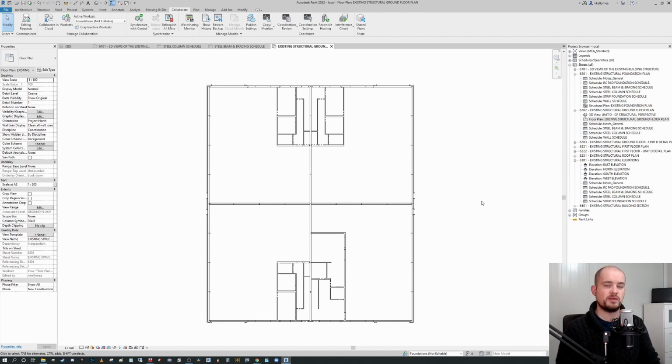And historically Revit, when you got to larger scales, lost a lot of finer detail. So if you had a very large facility, let's say, or a shopping center or something like that, and you were requested a couple of GAs, there'd actually be a lot of work in actually providing them at a scale, because what would happen is you would export them at 1:500, 1:1000, but you would lose a huge amount of data. All the smaller, finer data would be lost. They've really improved the amount of data loss. There's still a small amount of it, which I'm going to show you in a moment, but it's negligible compared to what was happening previously.